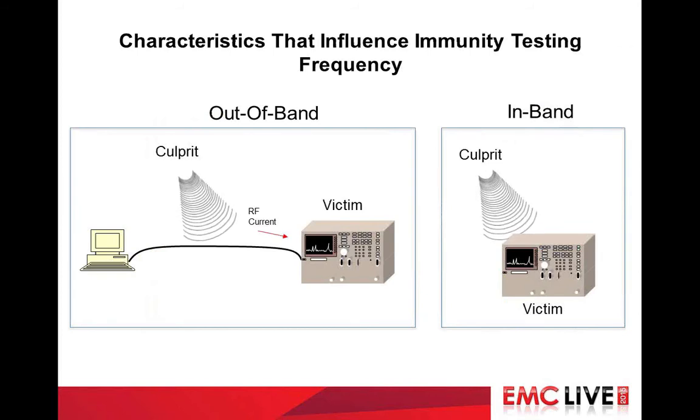For an RF device, there is an in-band immunity and out-of-band immunity, or susceptibility. The in-band comes from the culprit frequency or its harmonics coupling at the victim's tune frequency, harmonic, or IF. The out-of-band or non-RF device susceptibility generally results from the culprit frequency coupling into a circuit through an RF response window created by wire, cable, or resonance. Cable resonance is one of the most often occurring problems. Since the frequency responses are unknown, the entire RF spectrum must be scanned during an immunity test. Signals can be modulated or pulsed to determine if the system is susceptible.